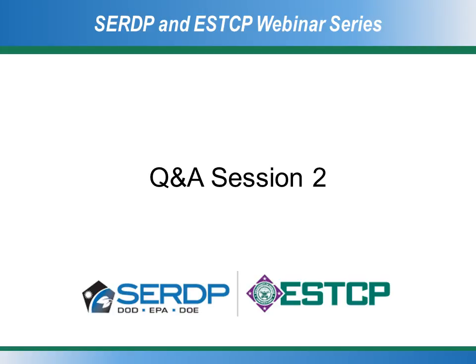Thank you so much. For you, Judy, you showed examples where ERT was successful in a field application. Are there any field applications where you would not recommend using ERT? So certainly if you're doing a monitoring application, you want to make sure the conductivity contrast, especially for an amendment injection, is going to be sufficient that you can actually image a difference. There has to be a contrast in the subsurface, even if you're going to do a characterization image. Are you looking for a lithological boundary? There has to be some contrast for you to image.